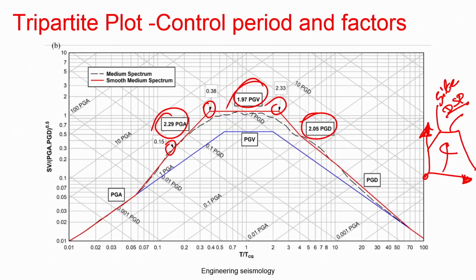As we know, India has two types of seismotectonic setting, majorly. One of them is peninsular India, which is a stable continent kind of region. The other one is the active region, which is very close to the plate boundary, like the Indo-Gangetic basin and the rest of the in and around region. These are the two major classifications you can define. Even if you want to go to a minor level, you can classify the northeast part separately. When we talk about the seismicity of India, we will discuss in detail how these regions can be divided differently. Right now, we have the same spectrum throughout the country.